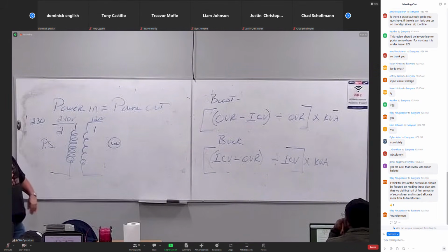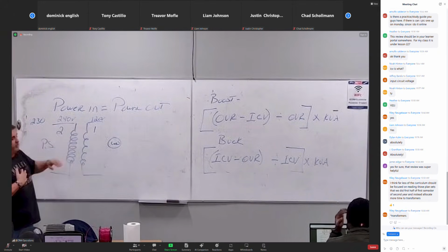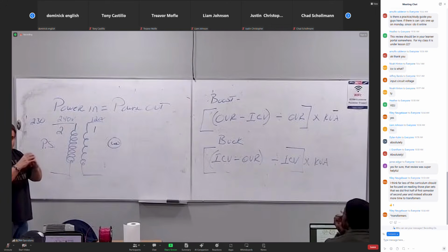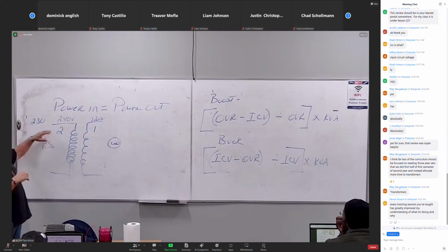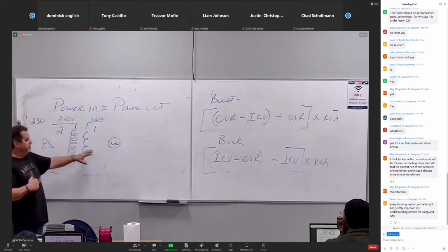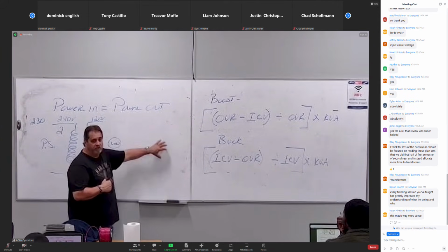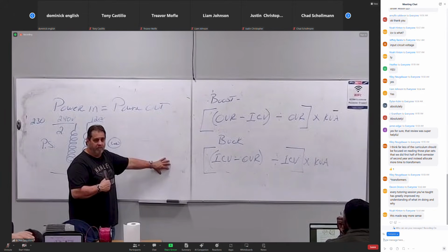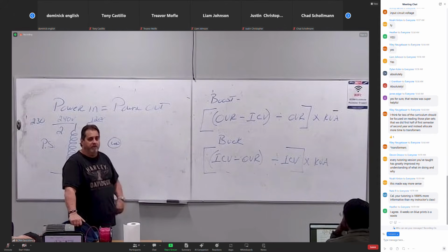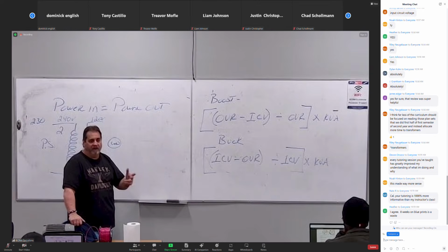So what I'm trying to get you guys to do and what I try to teach is say, hey, let's just make this make sense. You guys did it right here. 240 into 120, right? That's a 2-to-1 ratio. That's nameplate. That's how it's built. So when you get a nameplate value, that's your ratio. You don't get to change that ratio on basic transformers, okay? I can change my applied voltage though. So if I change my applied voltage, it doesn't change the ratio. That's the hard part. Once you get that part, then you can take your load, you've got power, you've got your voltage, you'll solve your current, right? It's just Ohm's law, P over IE. Every load has 3 components. And we say 4. Sometimes they put the resistance of the coil in there. Then you gotta find it yourself, but.